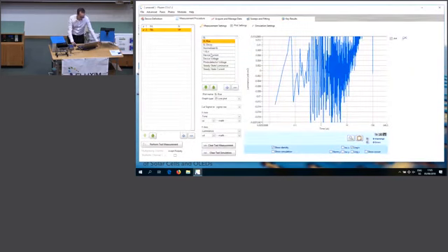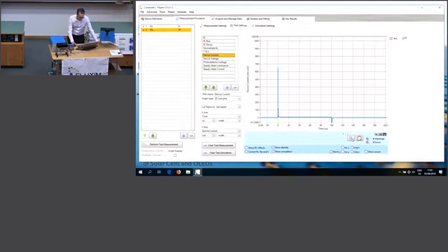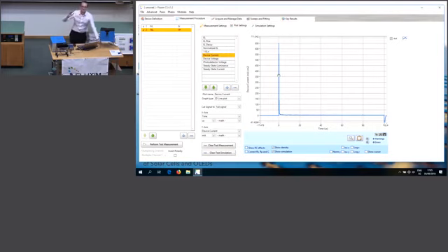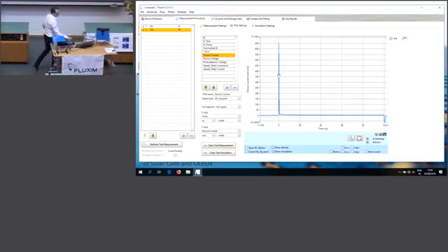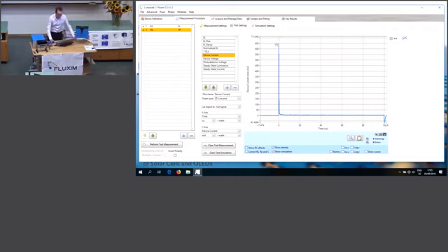All right, so let's first look at the current. You see there's a large peak, a displacement current. Now I can also show it with the mouse. There's a large displacement current here. This is because of RC effects, and then there's also a small steady state current.